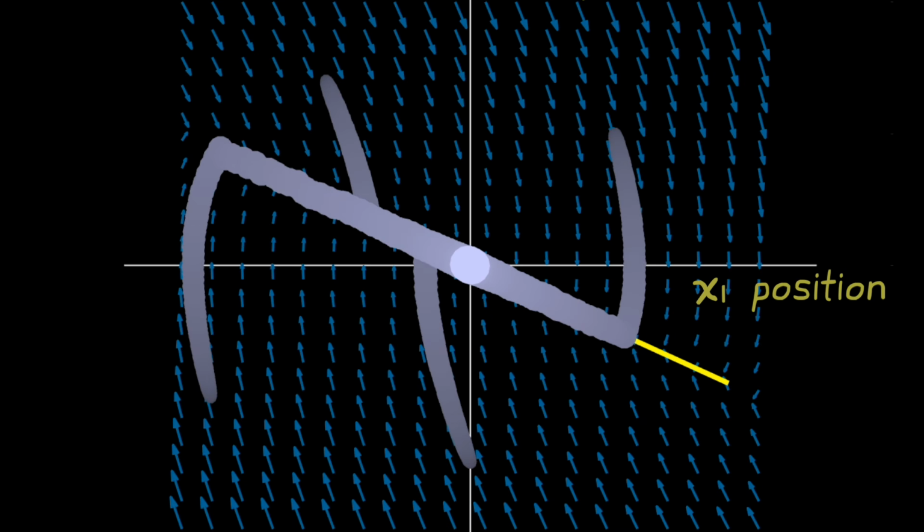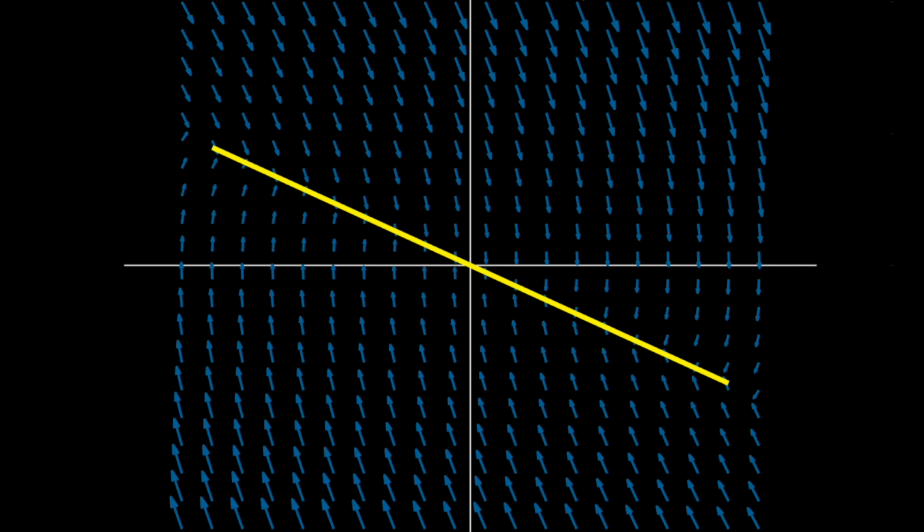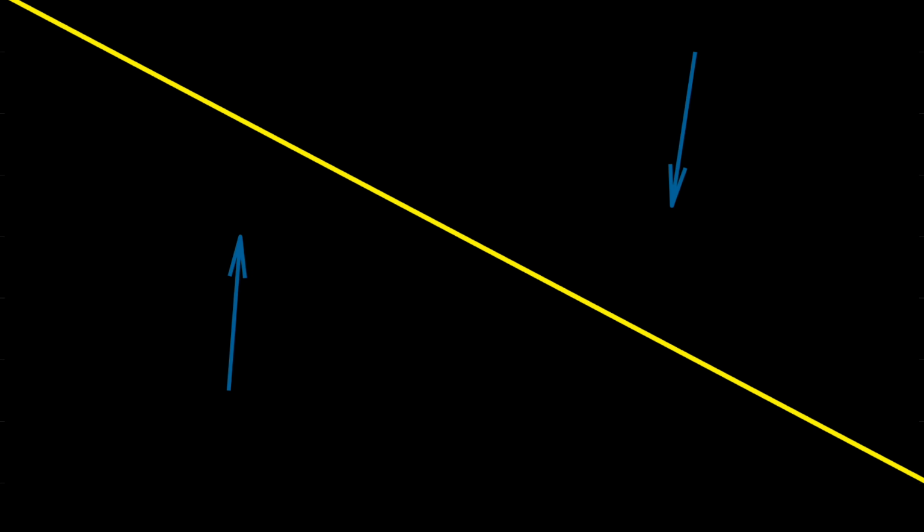Now, it might not be obvious at this point why this is actually a robust control strategy, but with this diagram we can start to understand it. Let's zoom into the phase plane, right at the sliding surface, and let's look at these arrows that are pointing in towards the yellow line. From their starting point, both blue lines are pointing in the correct direction, just like we want. But let's say that there's some external disturbance that we didn't account for.